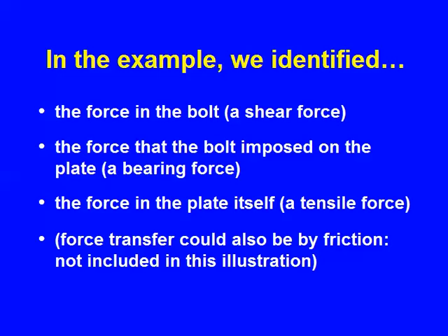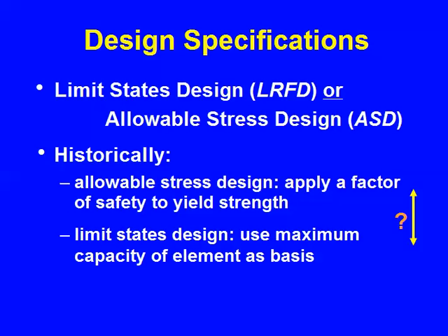Now, design specifications. You've got so-called limit states design, or LRFD, or you've got allowable stress design. Historically, allowable stress design said identify the yield strength and apply a factor of safety to it. Limit states design, which came along later, said use the maximum capacity of the element, in our case a bolt, or in your case something else, as the basis for design.